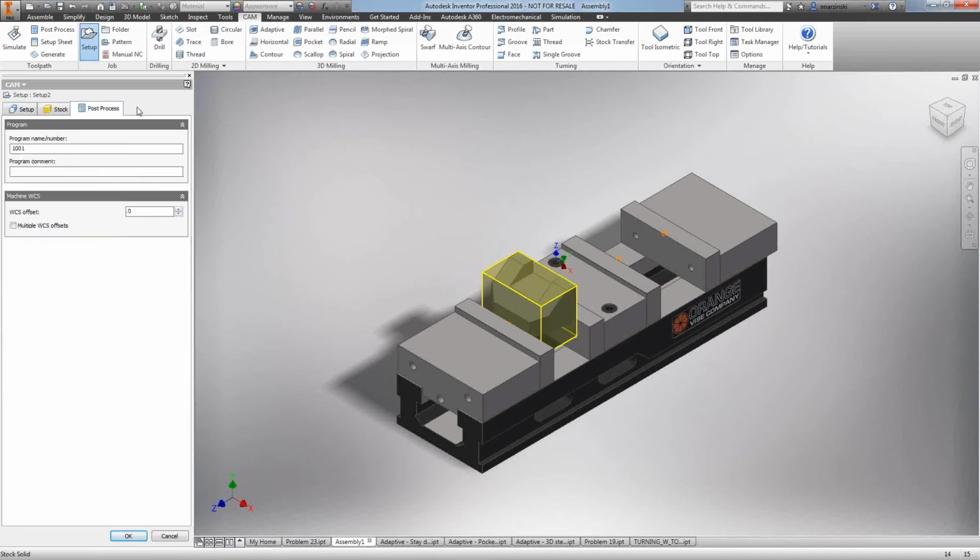There we go. And then the last tab here is post-processing. If you guys have multiple vice setups inside your mill, you can set that up here, do multiple offsets, enter the number of duplicates, and then you can actually preserve that to post out by order, operation, or tool. So let's say you have 4 vices set up. If I do it by tool, it'll actually post out to come in and face off all 4 parts before it switches to an end mill, for an example.